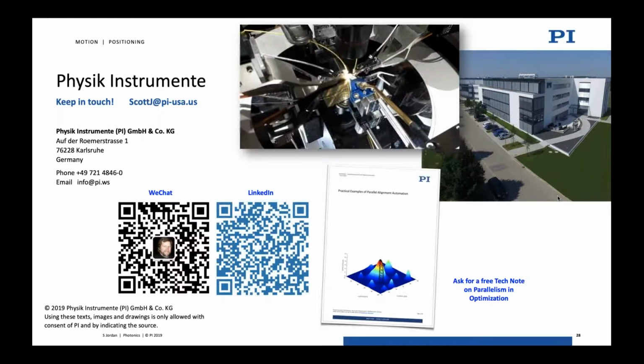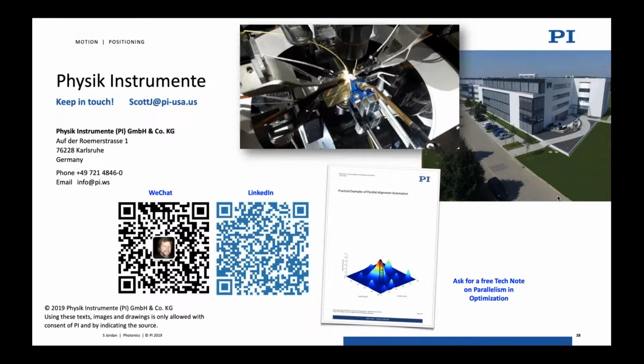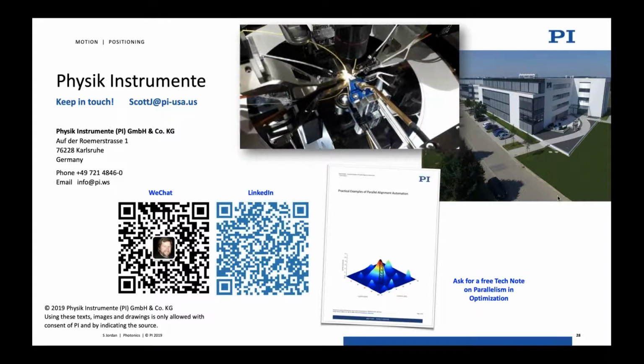So I went home, same laboratory here, and programmed an Arduino, a little microcontroller, $12 off of Amazon, with a little DAC chip to query the RSSI port. What comes back is a number, and I would output that to the DAC, and the DAC would create a voltage that could be used as the figure of merit for our systems here.